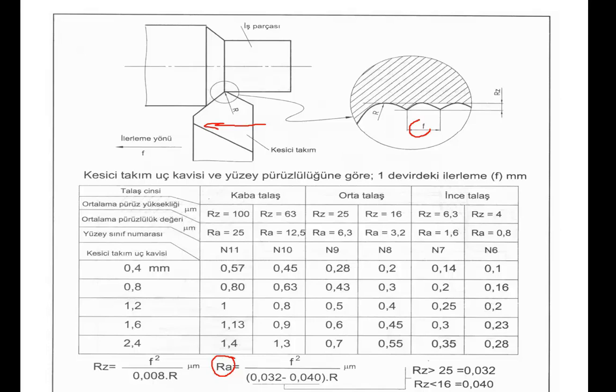Okay, say that the machine is a turning machine, the process is the turning process. Well, this is the workpiece and it is rotated by the chuck of the lathe machine. While it is rotating, the cutting tool is moved in this direction, and well, we have the cutting force over here to overcome the atomic bonding forces. We're cutting the material. For one turn of the workpiece, what is the displacement of the cutting tool? For one turn, the displacement of the cutting tool is f.